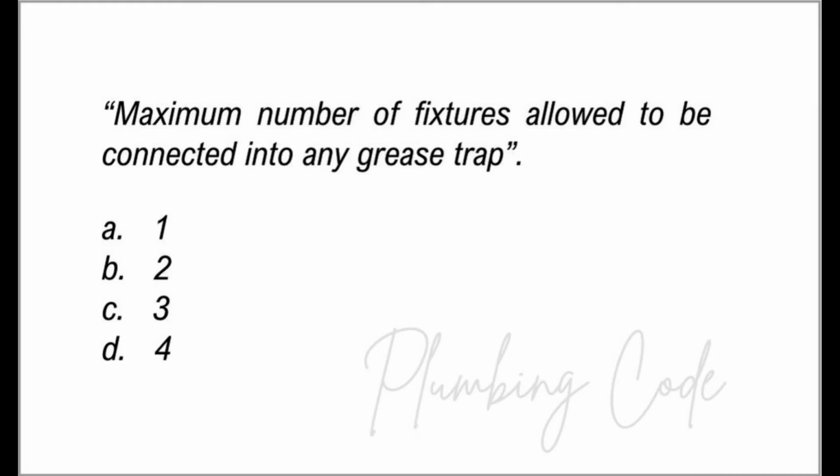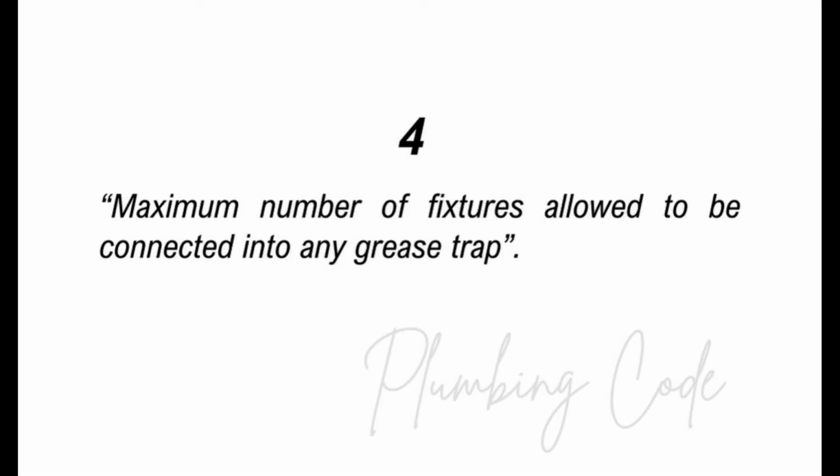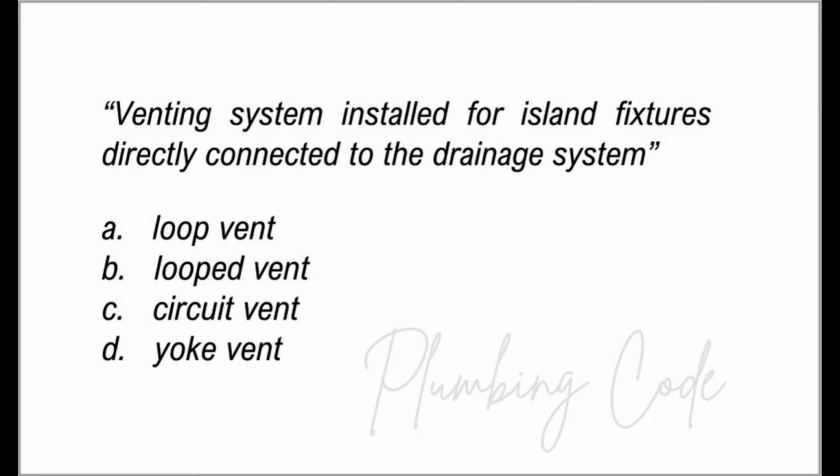Maximum number of fixtures allowed to be connected into any grease trap. 1, 2, 3, 4. The answer? 4 fixtures.